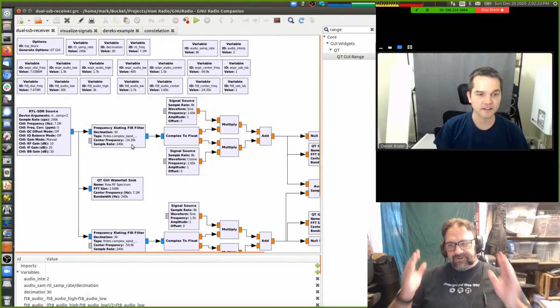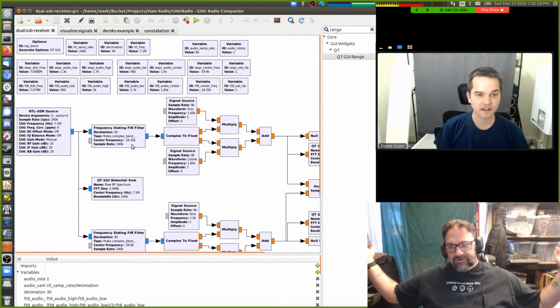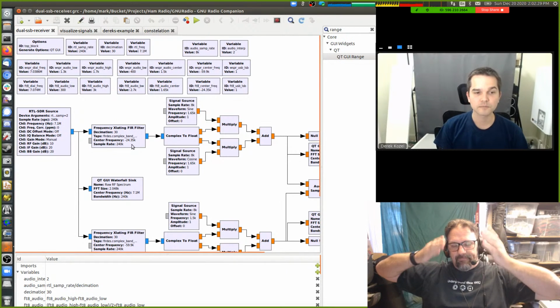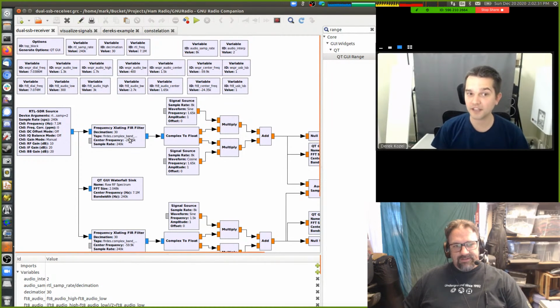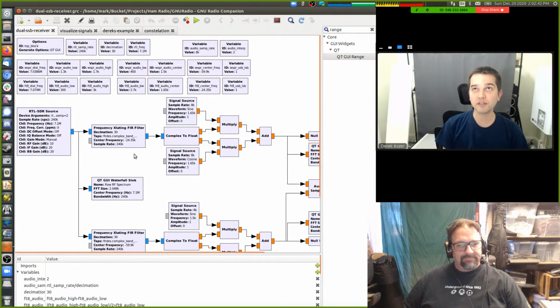And then the FIR filter is what ends up filtering out your out of band. You specify a bandwidth that you're interested in. So you want a limited bandwidth around this new center frequency. And so we want to decimate by a factor of 30. But if we basically kept one sample, threw away 29 samples, which, by the way, if you're following along at home and you want to have fun with this, there's the keep one in n block that you can use to do this. You could have it keep one in 30 samples, and that would be a decimation of 30.